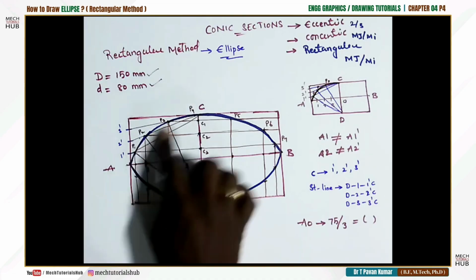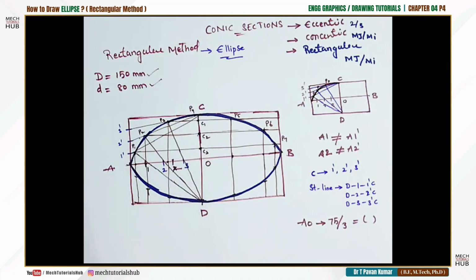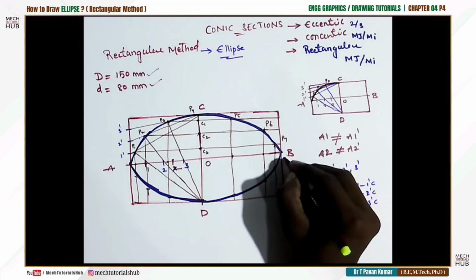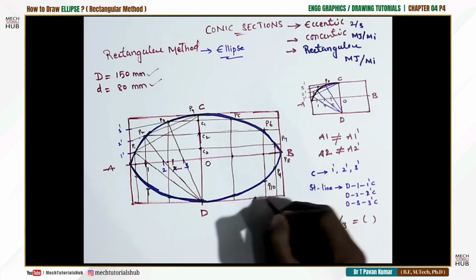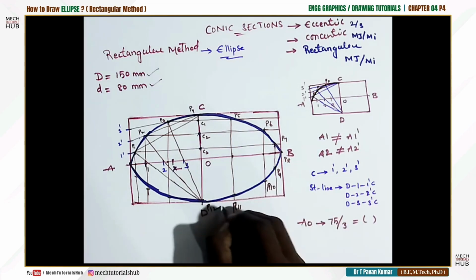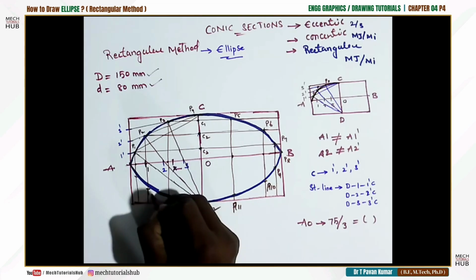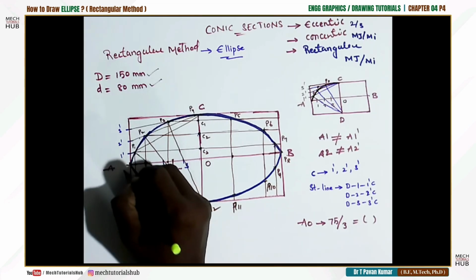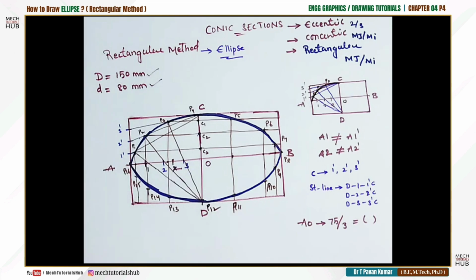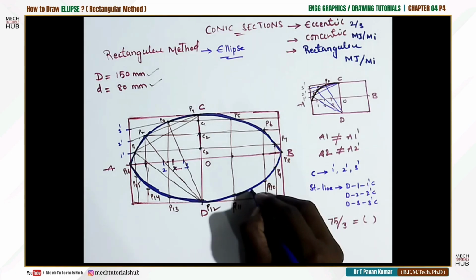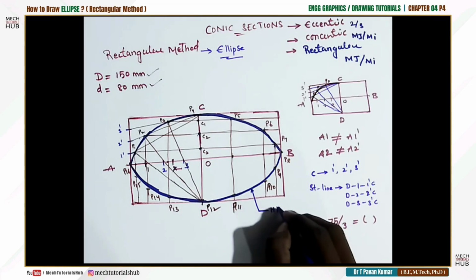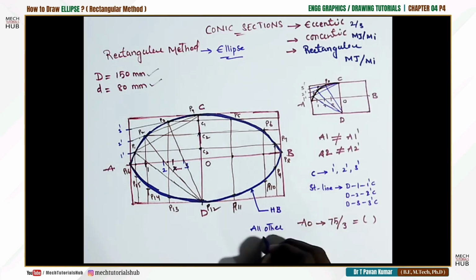Now our ultimate aim is to develop an ellipse, only that has to be darkened. After P7 it is going to P8, P9, P10, P11, sorry, P12, this becomes P13 and P14, P15 and this becomes P16. The point A becomes P16. This is how you need to develop an ellipse, and only the ellipse sketch has to be darkened. That has to be drawn with HB pencil. All other construction, numbers or letters need to be with 2H pencil.